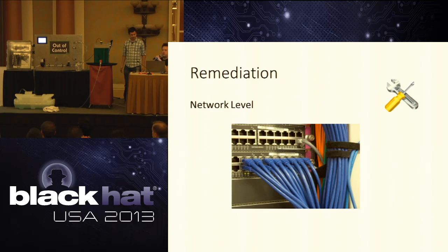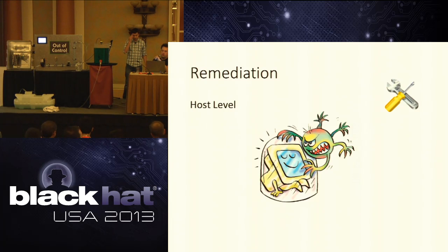So quickly, I'll talk about some remediation. A lot of the network security is similar to the enterprise side. Making sure your architecture is compliant, with standard architecture with firewalls, and trying not to have a public IP for some field devices that anybody could just talk to. Host-level antivirus is old and antiquated, but it's still the best practice, so it's still used a lot.